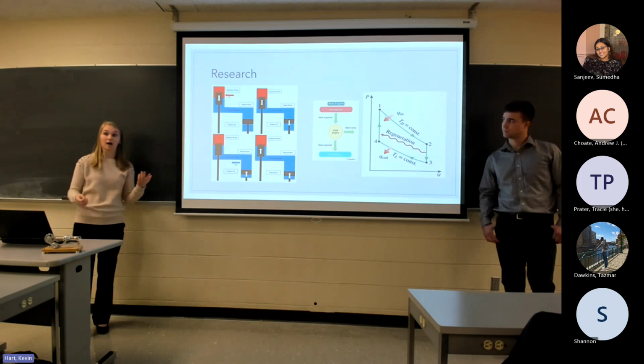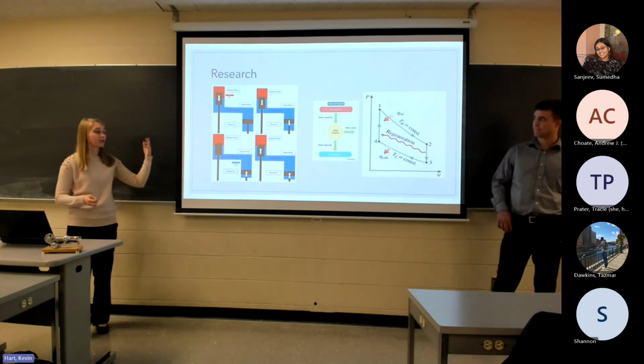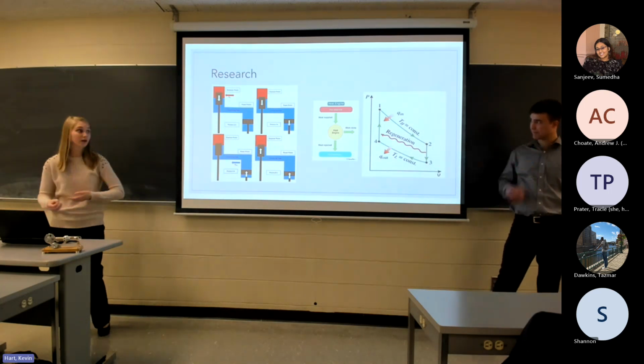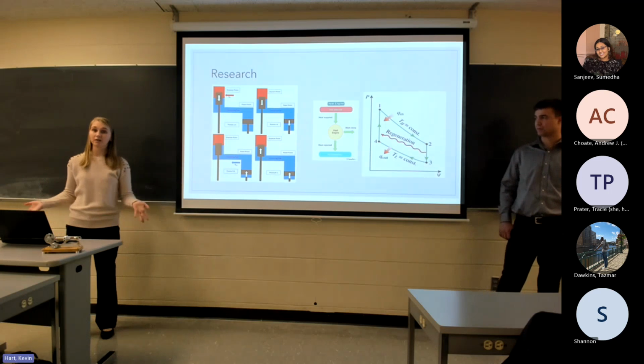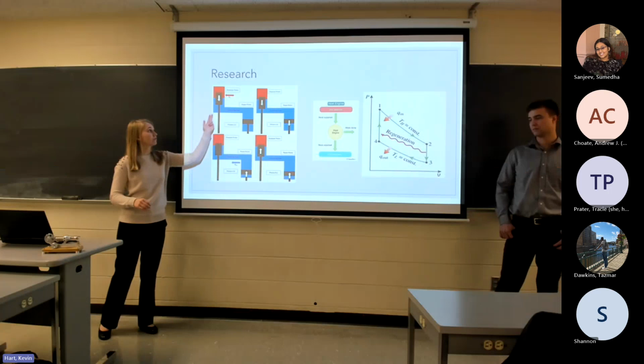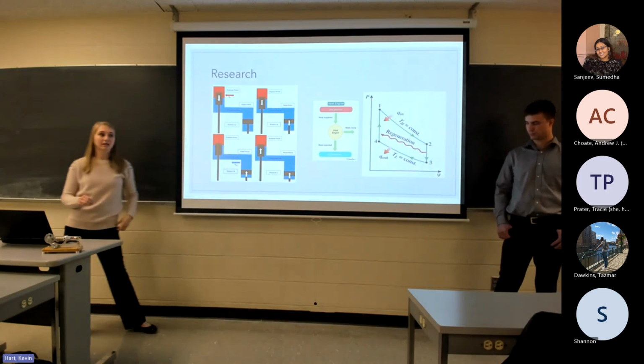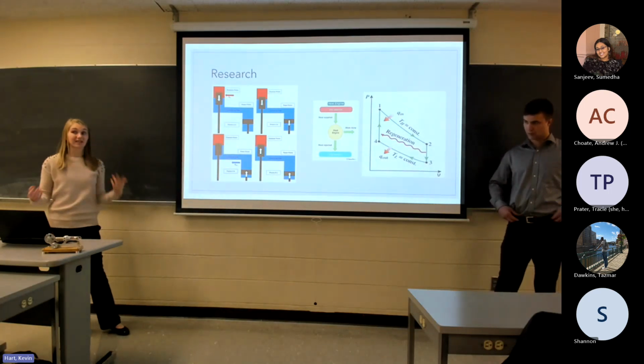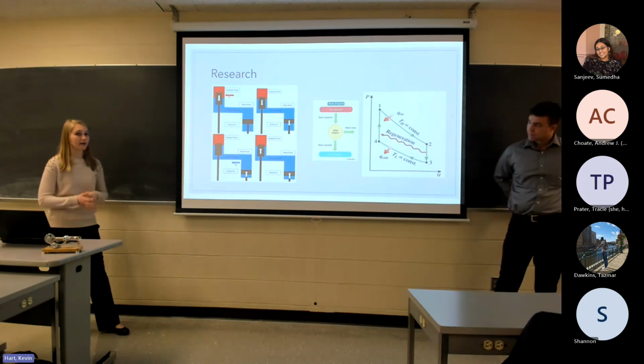We've also researched the different types of Stirling engines. So as you can imagine, the gamma type is not the only one that we have. There is also an alpha type Stirling engine in which the hot reservoir is connected directly to the connecting tube. This engine has a lot of dead space in it, so we decided not to go with it.